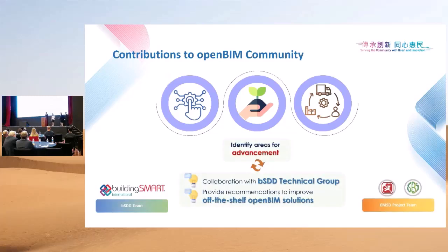Yes, Beverly. So during the development of automation for the bSDD and IDS generation, we were in continuous coordination with the BSI technical team. During the project, we have transformed roughly 1,800 bSDD properties and 7,000 plus IDS checks for the project. The BSI technical team has also helped us to refine the bSDD schema itself to support various edge cases. For example, they have increased the regex expression length from 200 to 3,000 plus characters to meet the project requirements.